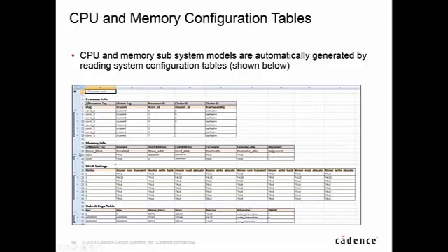Then we go into the resources of what memories are available and what address ranges those cover, and then we go into the memory access indirection register settings, to get those set up, and then also the default page tables, as Adnan was talking about, the whole DVM configuration capabilities that need to be set as well.